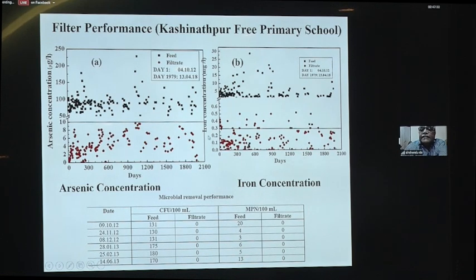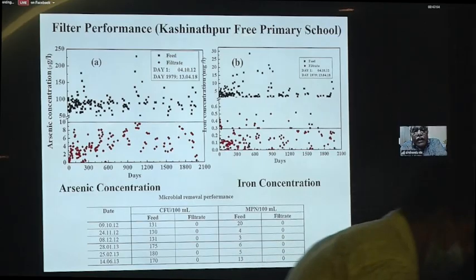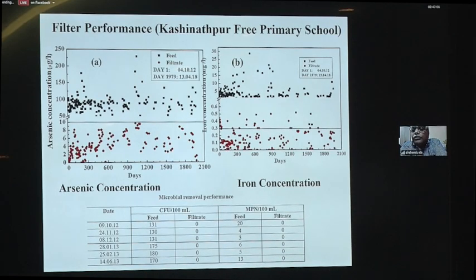during these 6 years. Similarly, the iron concentration in the feed varies from, let's say, 5 to 30 ppm, milligram per liter, whereas the allowable concentration in the filtered water is 0.3 ppm, and the red dots show that in most cases they are very close to 0.3 ppm. For any filter, the WHO limit for microbial count is that total bacterial count should be 0.